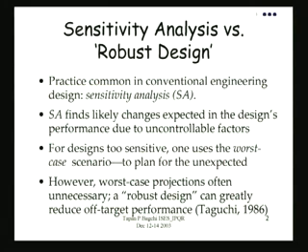We started with, for example, robust design as a philosophy. And this is different from sensitivity analysis, because here you are also trying to incorporate Taguchi's philosophy that things should be on target and then they should be robust. If you just do sensitivity analysis, let's say I completed the design of a product, then I vary one or two factors, and I see the impact of that on its performance. What that really does is it just gives me one factor at a time type of sensitivity. I really am not doing robust design type of experiment when I'm really doing sensitivity analysis. So this is something you've got to remember.